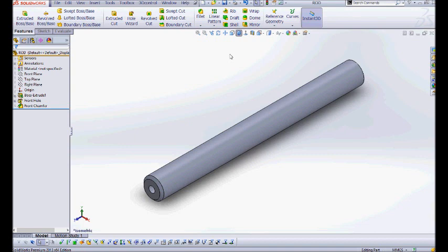So this hole was in both places, so it's an open sketch, because he did not select the plane first, and then select Hole Wizard. Click on the face. Okay, help him and I'll come over. Yeah, open Hole Wizard. And hit the same.